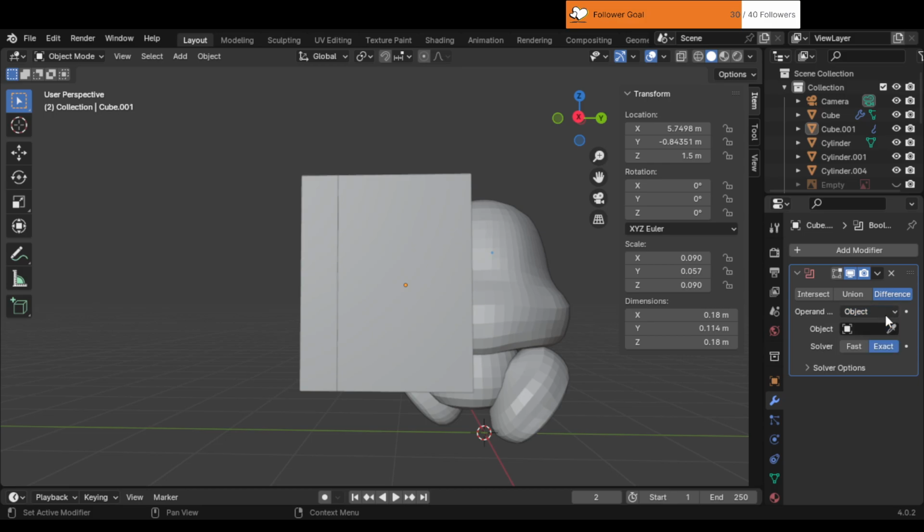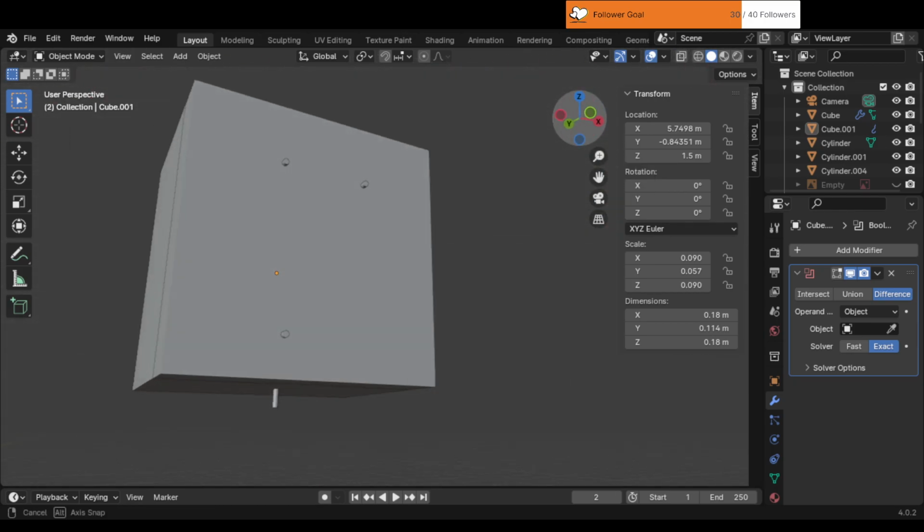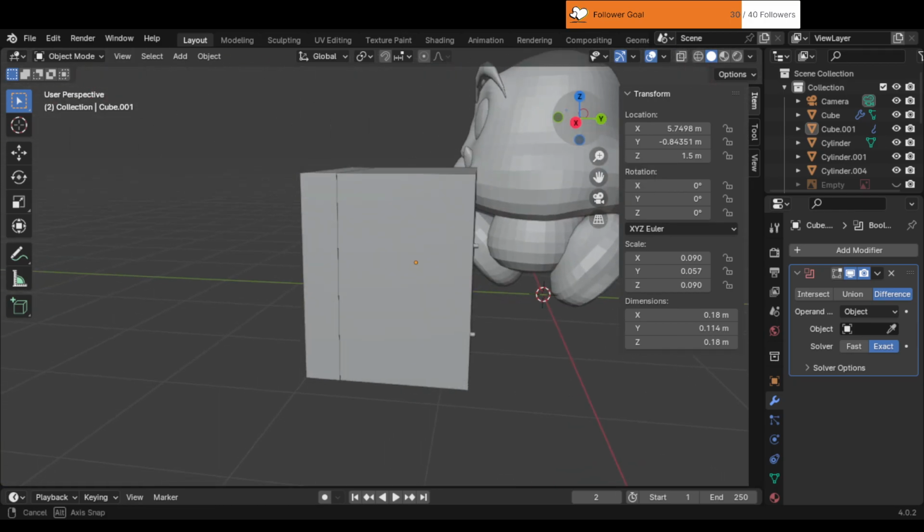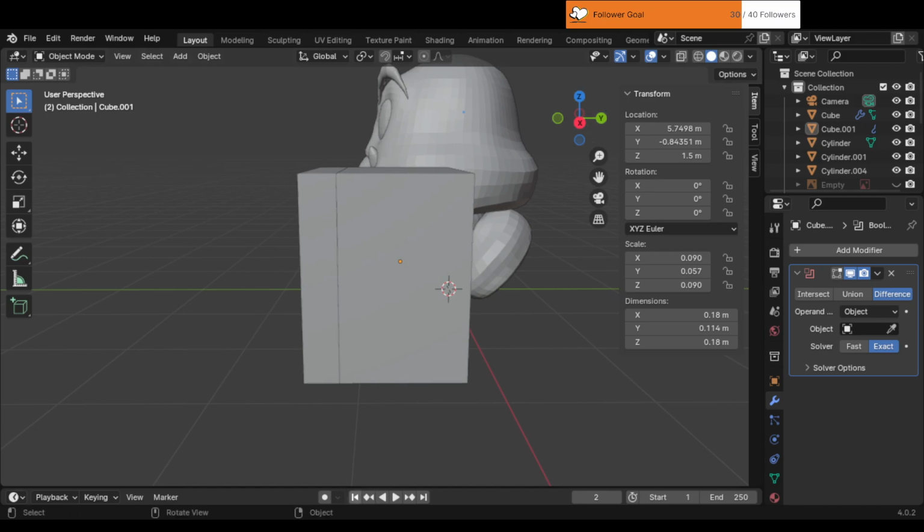2. Verify meshes for manifoldness. Non-manifold geometry. Check both your container and model to ensure they are closed, manifold meshes. Boolean operations can fail or produce unexpected results if the meshes are not manifold. Normal orientation. Ensure that the normals of both meshes are facing outward. In edit mode, select the mesh and check the orientation of the normals. Alt-N, recalculate normals.